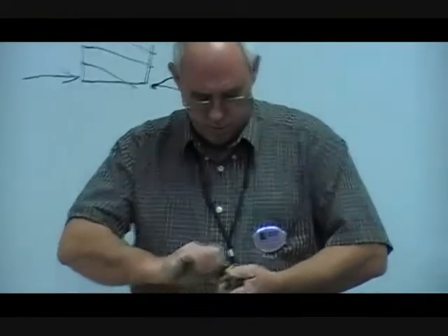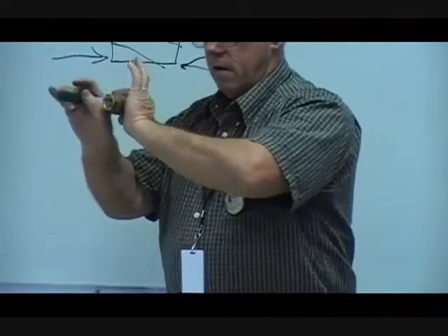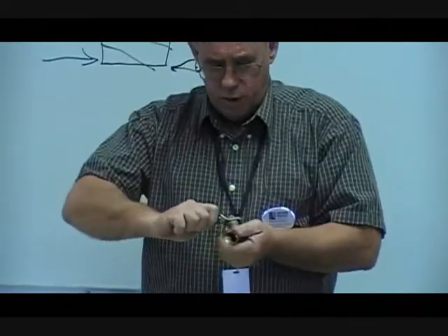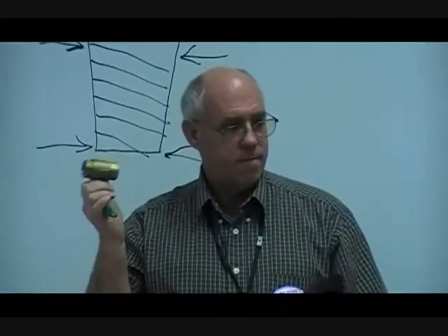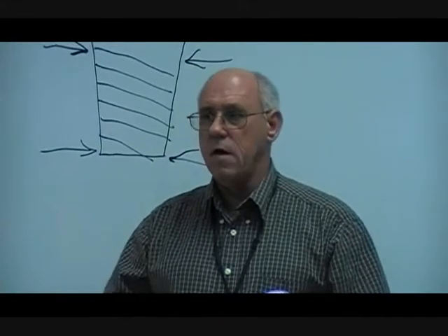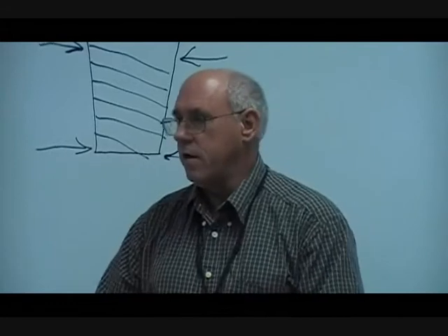All right. Some of the other fittings that I want to just point out that we use in pipes. This is a ball valve. Okay? It's a full open port. I don't know if you can see that or not. Okay? Look and see what the valve is rated for. Some valves may not be rated for gas line. They may be rated for water or other fluids, but look and see what they're rated for. Look and also see what the pressure rating is.